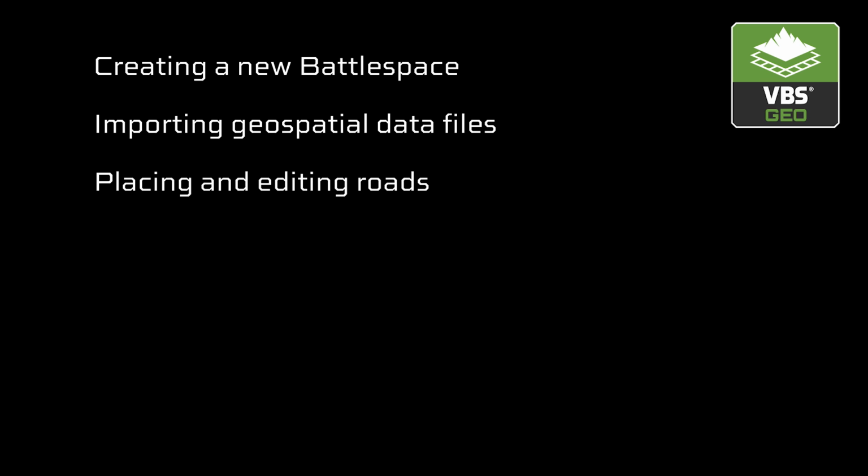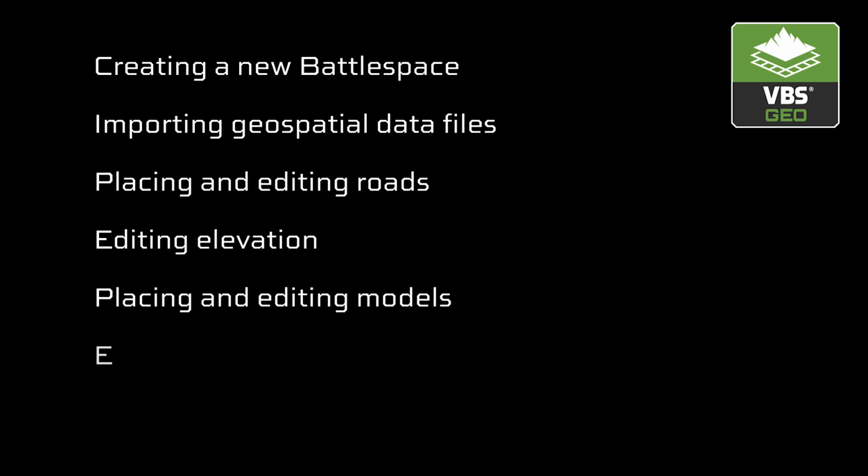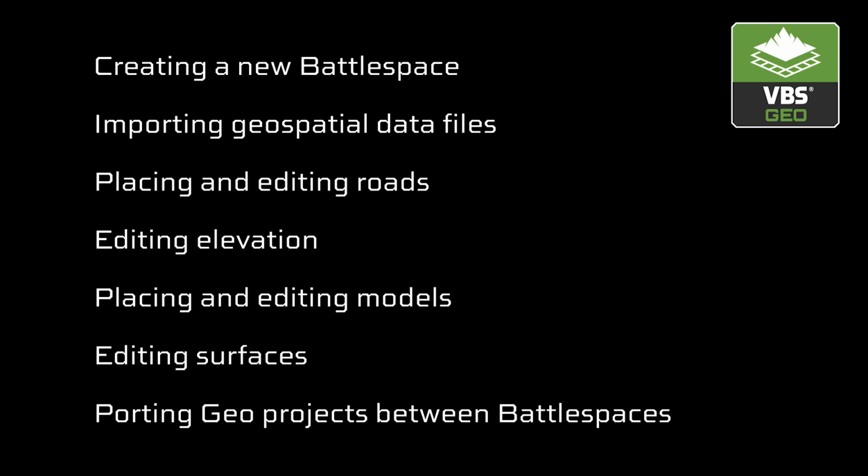Hi, I'm Ross from the Geo team, and today I'm going to be showing you how to create a terrain from scratch using VBS Geo. This will involve creating a new battle space, importing geospatial data files, placing and editing roads, editing elevation, placing and editing models, editing surfaces, and finally porting geo projects between battle spaces. Let's get started.